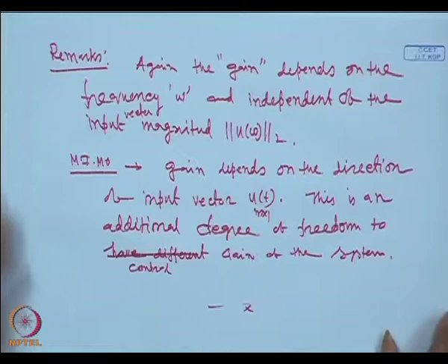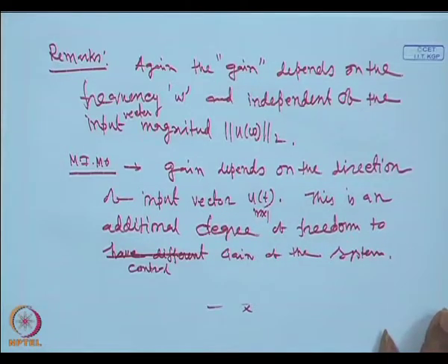But in a single input, because there is only one input, the gain depends on the frequency. For multi input, it depends on the frequency, and we have another freedom to control the gain of the system, that is the direction of the input vector.